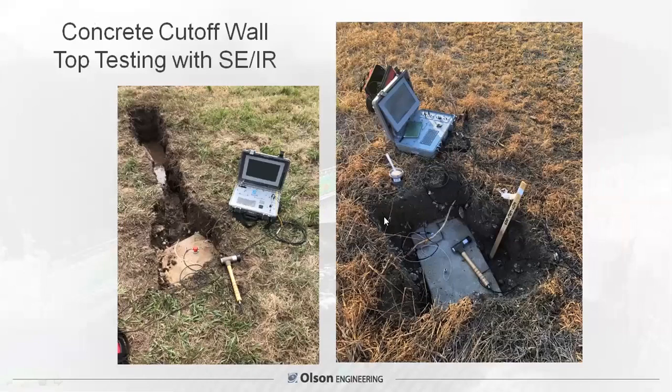This is another unusual application of the echo testing method. This is a buried cutoff wall. You can see the top of the wall is actually under the earth. This was excavated out for us. And this cutoff wall extends for quite a distance. And we were looking for depth and integrity of the cutoff wall at selected locations.